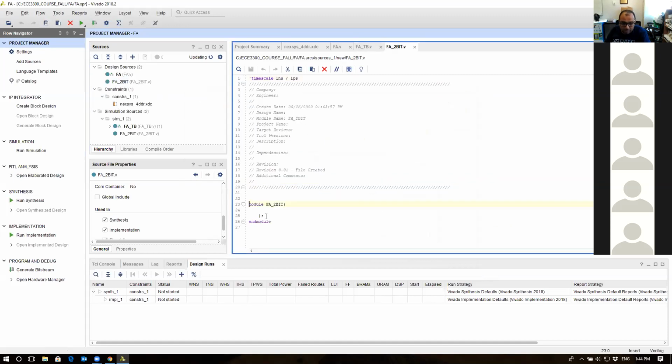All right, so I will go here and I will say A input, right? So it's input, but this time A is not a single bit. A is a bus. So basically I will open here and say [1:0] and I call it A. Input also [1:0], B. Then input carry in, it's the same, but to be consistent, CN.